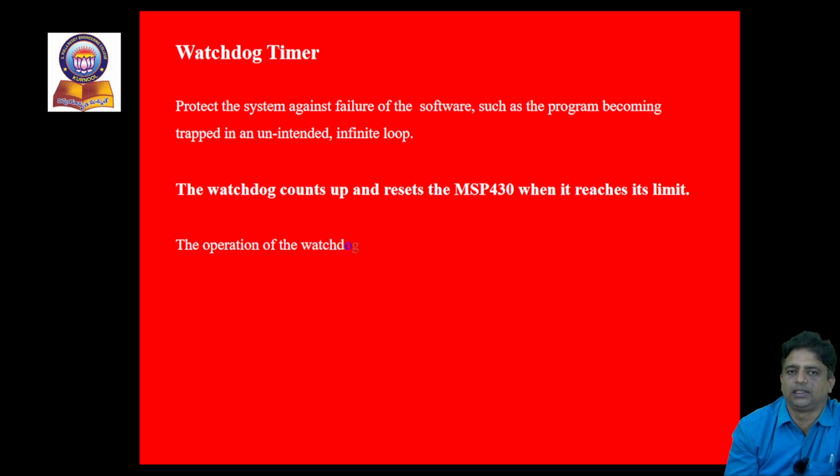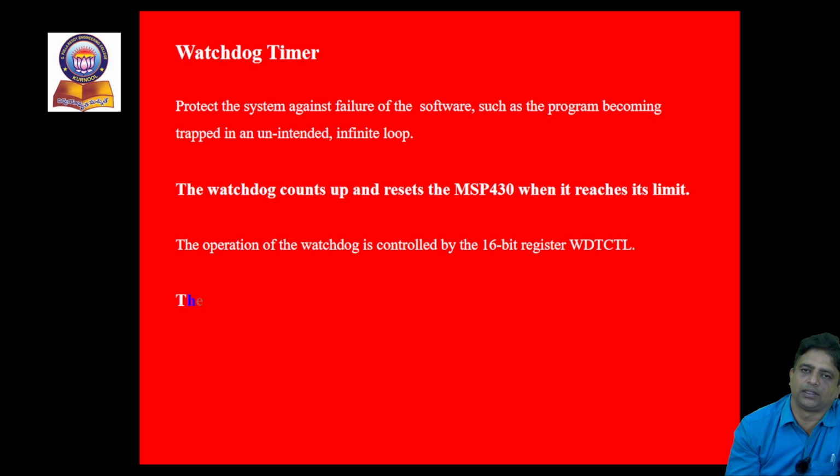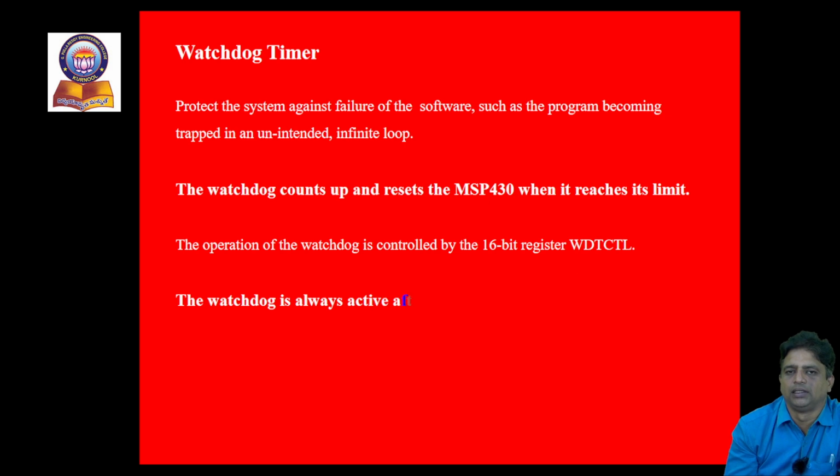This happens in a technical way based on some time constant. According to the design given for the watchdog timer, every 32 milliseconds the watchdog timer has to go to the CPU and invoke it back to its active state. So this is a duty given by the MSP CPU ALU itself. Every 32 milliseconds, the CPU should reset this.